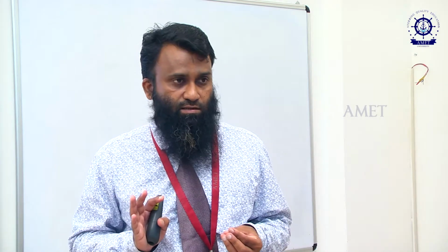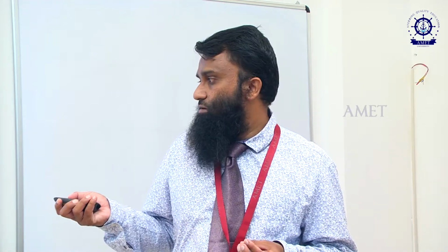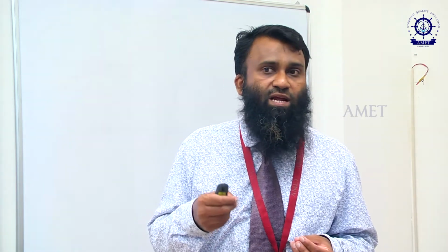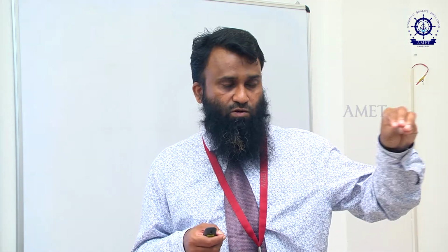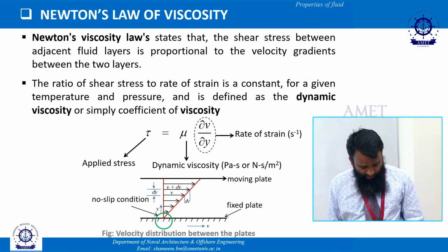If more viscous, we know that more force is needed to move. How can the viscosity vary? If the temperature is more, the viscosity can come down, it will affect my force of movement, correct. So that is very important. Basically the viscosity is a factor which depends upon the temperature. So whenever we do an experiment, we have to say the viscosity of the fluid at this temperature, that is important.